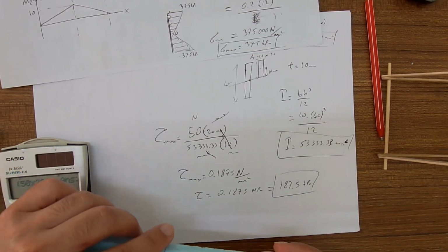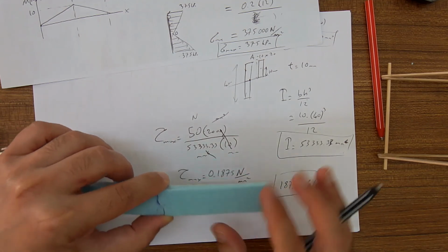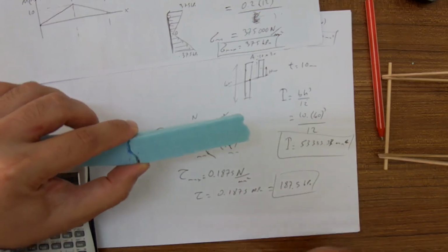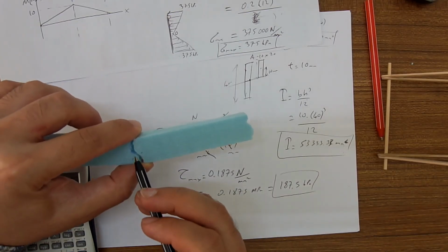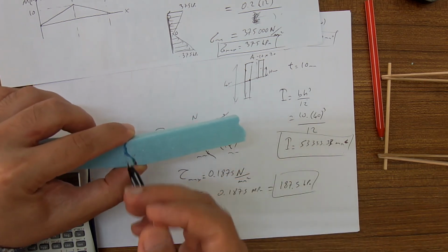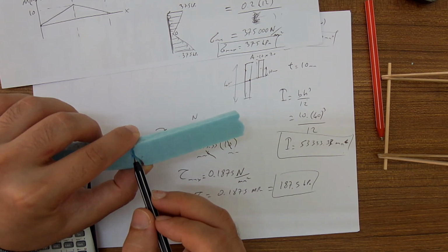But where the bending stress is small, the effects of the shear stress become visible. The bending stress gets smaller at the mids and shear stress gets larger around the mids. Therefore we can see the effect of shear stress.